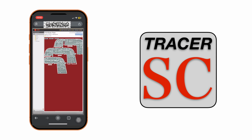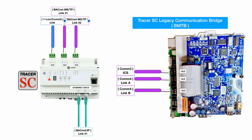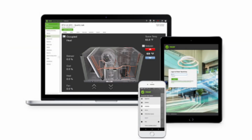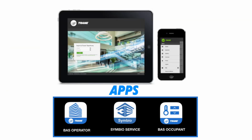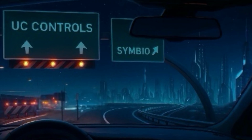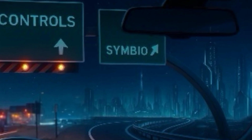The SC also brought native BACnet support, both MSTP and BACnet IP, while still providing gateways to legacy COM3, COM4, and LonTalk devices. Then in the 2020s came the SC Plus and its Synchrony platform, which refined this approach, giving users a cleaner, more modern experience with improved graphics and mobile access. But as Trane moved deeper into BACnet, it was clear that their controls needed to align more closely with the BACnet standard convention that the rest of the industry was adopting.